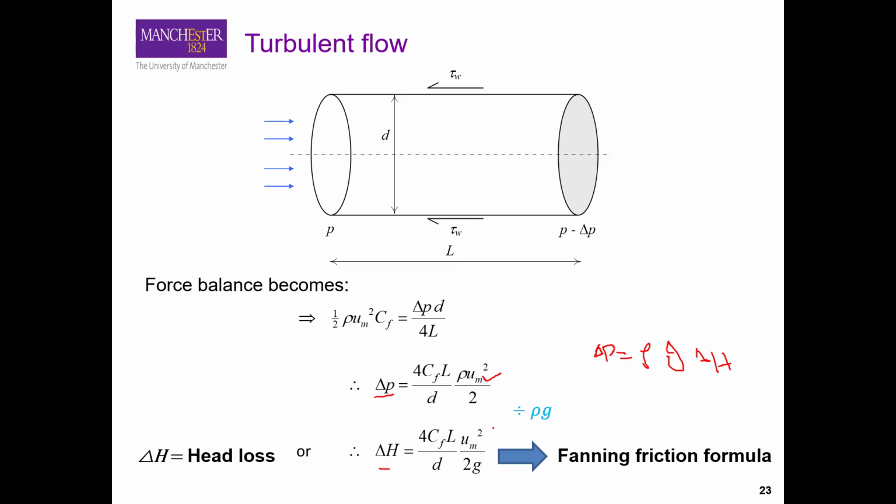So this is the formulation where you calculate the pressure drop or the head loss in terms of the friction factor, okay. By using this equation, you can now use, for example, the Hagen-Poiseuille equation, put the value of delta H in that equation, and calculate the flow rate of the system.